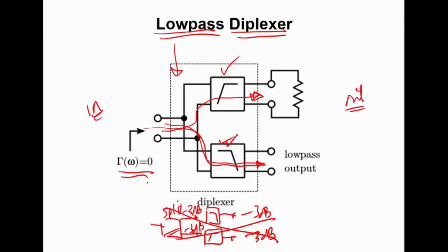Why do you use a diplexer? Well, aside from this issue with the insertion loss, this is also a convenient way to, for example, eliminate reflections in mixers. When we talk about frequency conversion, we will point out that a mixer, which has RF coming in and perhaps an LO driving the mixer, will have a ton of products here at the output that we don't want. So what's common to do is to put a diplexer in there.